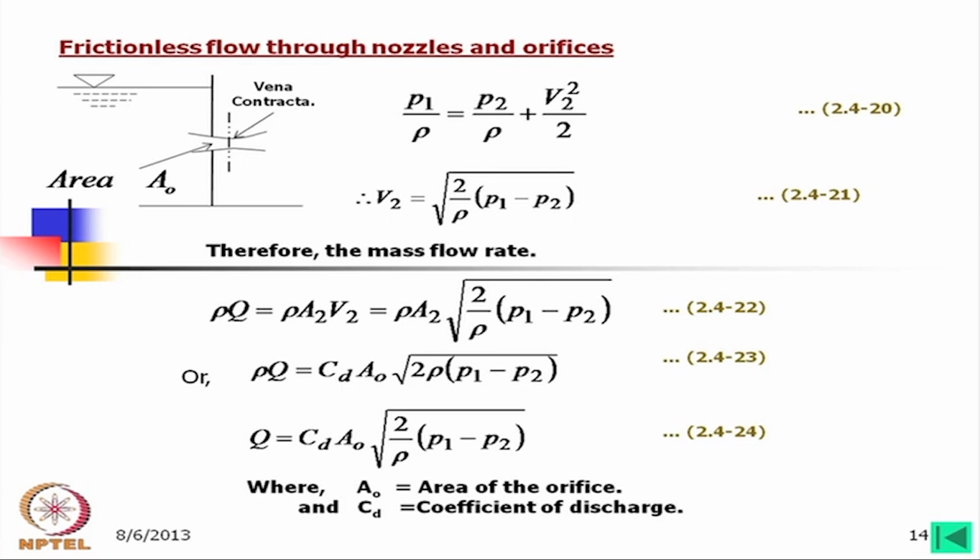Of course, that depends on the orifice area. In most calculations in fluid power, particularly in oil hydraulics, this Cd value may be taken as 0.62. Later, when we come to valve flow, I will show you how Cd can be taken as more or less constant for fluid power analysis.